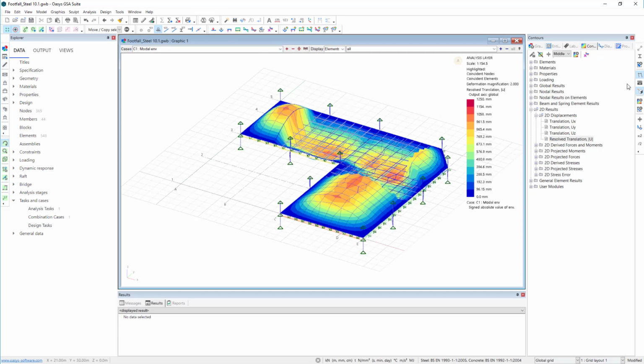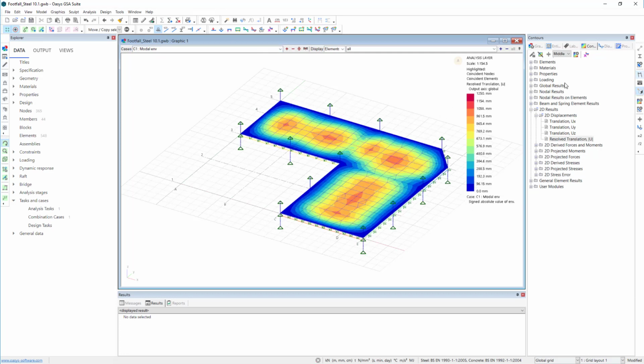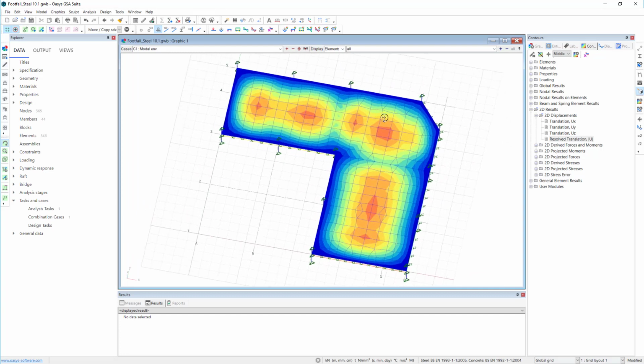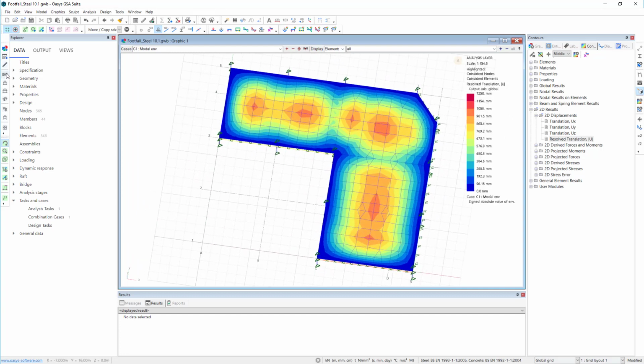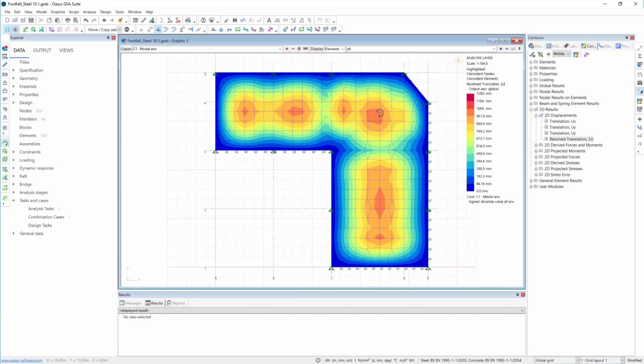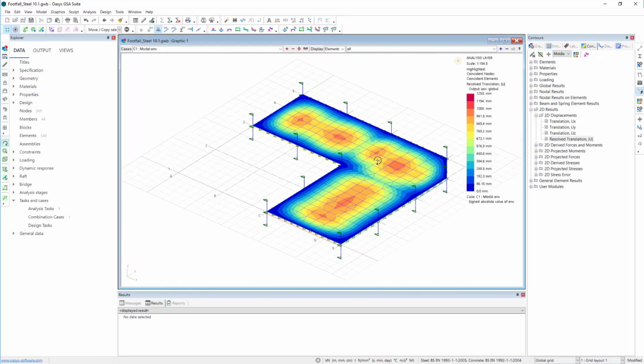Well, I should switch the shape off because I always get confused. And we can see that we've got pretty much all the peaks of interest. There are some zones here which might require higher frequencies, but unless that's particularly crucial, maybe we can get away without looking at those. All right, so I'm happy with the modes. Let's do a footfall analysis.